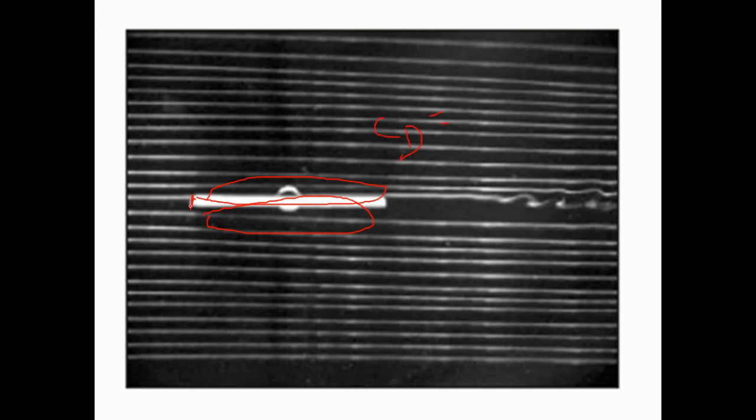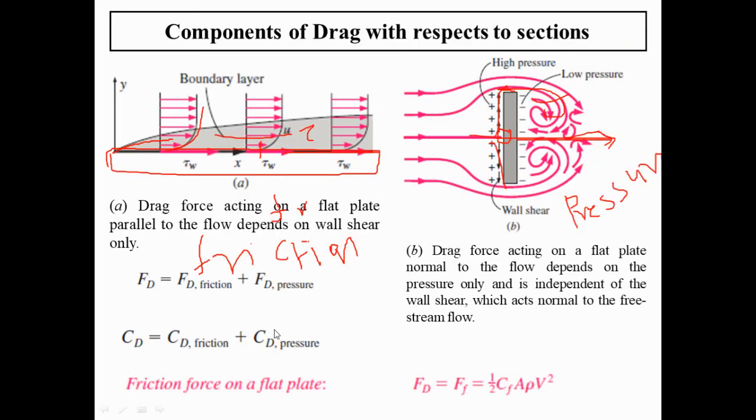The pressure drag you can calculate, which is nothing but the frontal area pressure. I'm first finding the drag force, which is nothing but half rho v squared into A. This will give you the drag. It is for the frontal area, and we can also add the frictional drag, which is half rho v squared A, where here you multiply with CD, and here we multiply with CF. This is the coefficient of friction. So you can see the frictional and pressure drag.